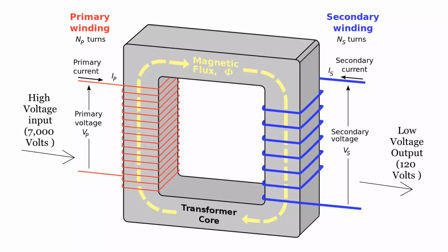If you coil a separate wire onto the same core, when the primary coil is energized, the iron will magnetically flux. This will cause an electron current to be induced within the secondary coil. It is this process by which the high voltage is transformed to the standard household voltage. The fewer the wraps of the secondary coil, the lower the induced voltage. A calculation will determine how many primary and secondary wire wraps are required to produce the desired output.